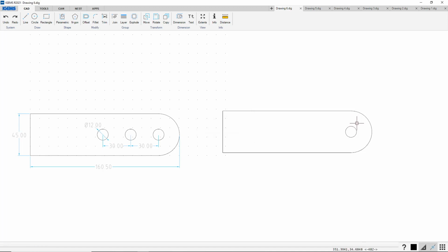And I'm gonna use the Shift C, our special copy command. So I'll select this part, hit Shift C, and if I hit enter or space, it will select the center. So I can do that, space. And I want to remove this 30 millimeters. So I just type 30, like that.